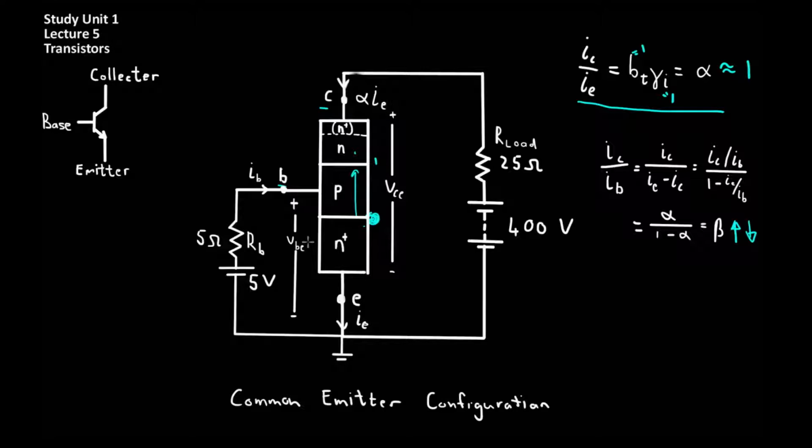An important factor to consider when using BJTs in power electronics is the mechanisms through which the transistor will break down. Referring once again to this common emitter configuration, there are two breakdown mechanisms which the transistor will experience as current becomes too large. The first breakdown is a gradual breakdown and occurs between the collector and the emitter. The second form of breakdown happens when the base is also included, and this is a more catastrophic breakdown.